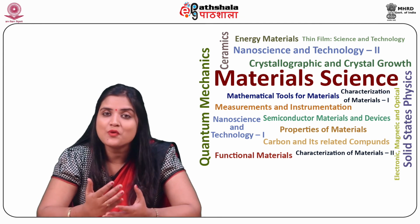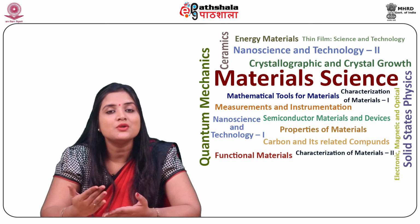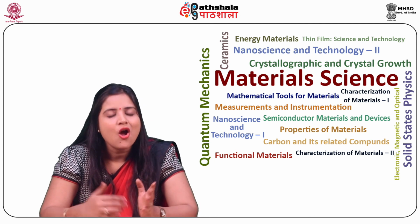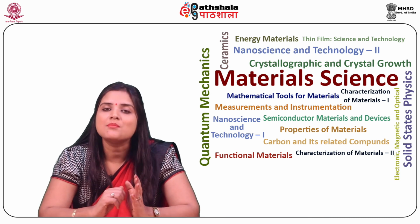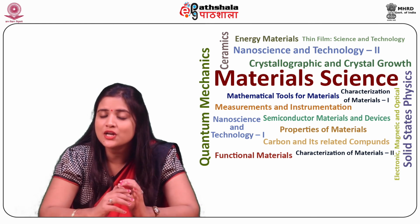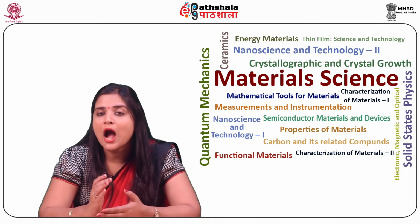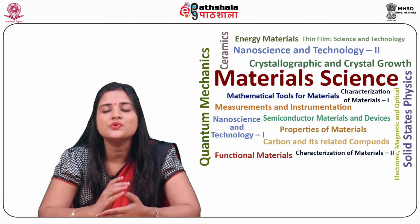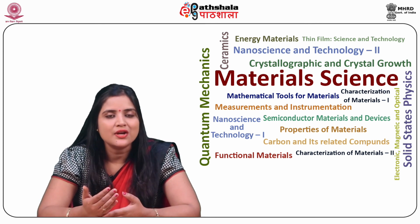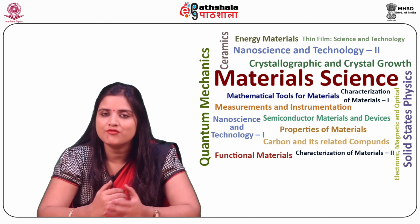The name is derived from the fact that the output voltage is equal in magnitude and in phase with the input signal. That is, the output signal tracks or follows the input signal in magnitude and phase. In order to obtain the voltage follower circuit for unity gain, we can see from equation 5 that RF should be equal to 0, that is, short circuit, and R1 should be infinite, which means open circuit, as shown in the circuit in figure 5.